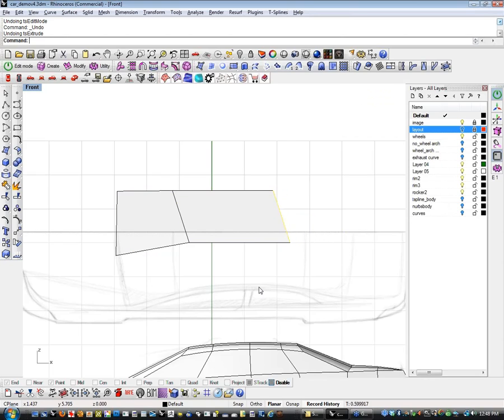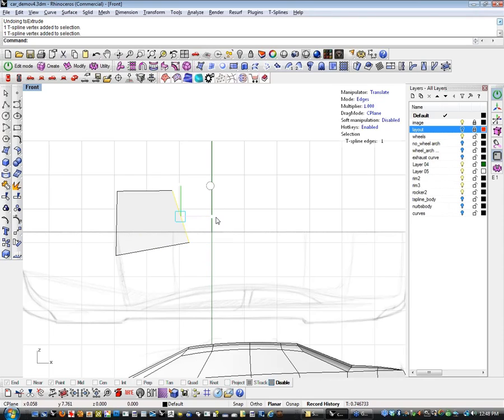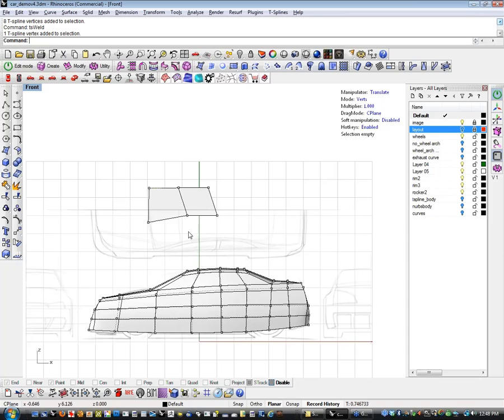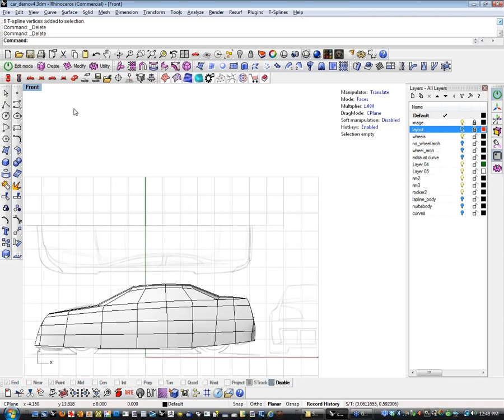It's already started. The second thing you're doing is transforming it. There's 2 actions that are happening. So to get rid of it, you need to undo and then undo again, because now I've got 1 vert there. If I just Alt-drag, undo, and Alt-drag, I've got 2 verts there. Want it, but it's easy to fix. Just select everything, hit the Z key. Coincident verts will collapse within file tolerance. That still doesn't answer my issue of why this model has creases in it.